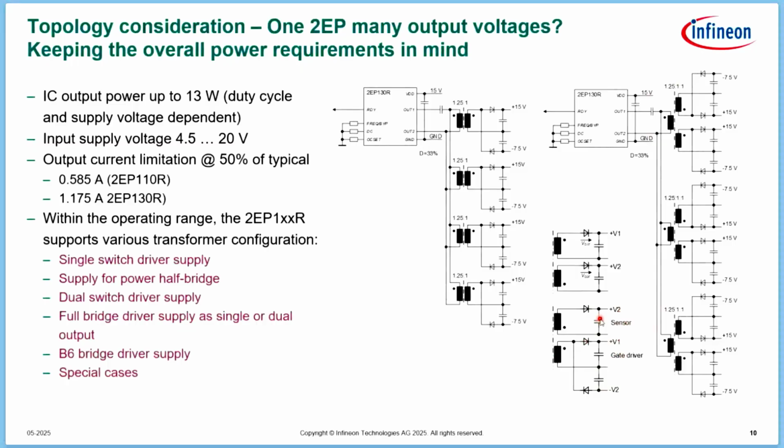Could be an ADC, which is isolated and needs an output voltage. Could be another rotational sensor or something like that, which can be supplied via the same stage, just using these same transformers. Or saying, I want to have just two different output voltages, one positive, one negative, and having them with the rectifier diode turned over into two positive output voltages. All this is basically possible.